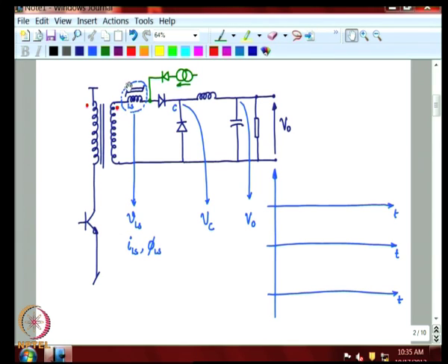And initially the inductance acts as an impedance on open circuit and does not allow that voltage to appear at this point in order to forward bias this diode or appear at this point till that gets saturated. So, let us look at the current and the voltage wave shape of the inductor Ls.